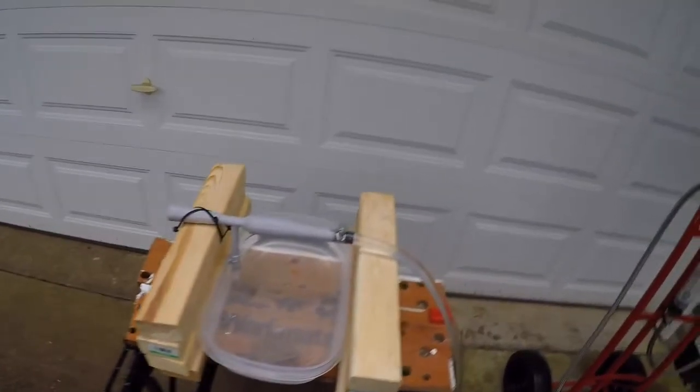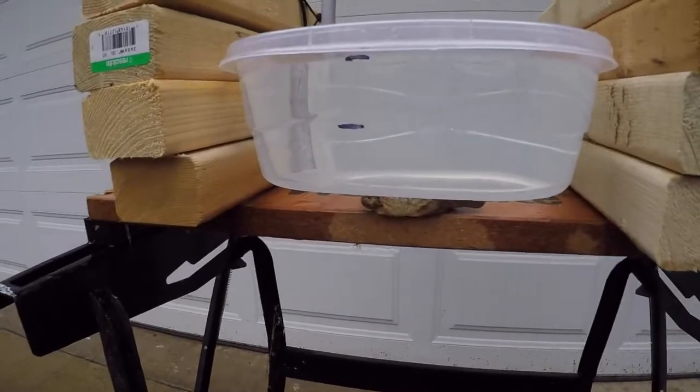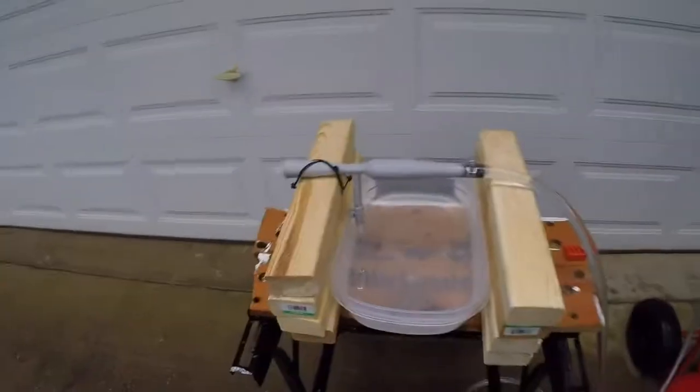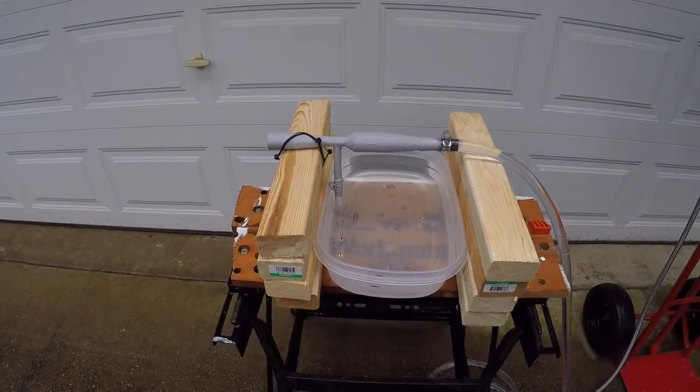So for our last clip here, we have a video of us measuring the actual flow rate at the suction end of our Venturi. So you can see on this bucket here, we have half a gallon and 1 gallon marked. So what we'll do is we'll turn on our Venturi and we'll let the system flush itself of any air bubbles that may be lingering in it.